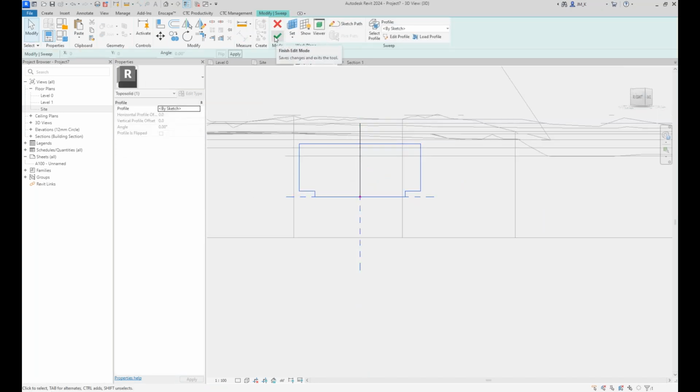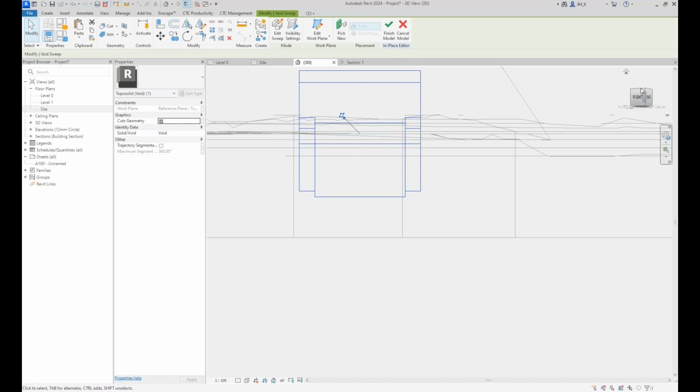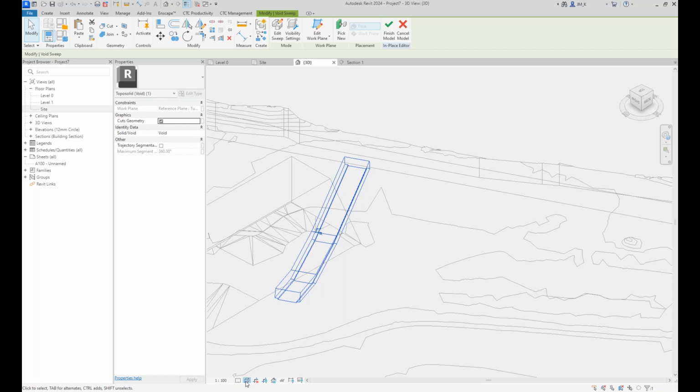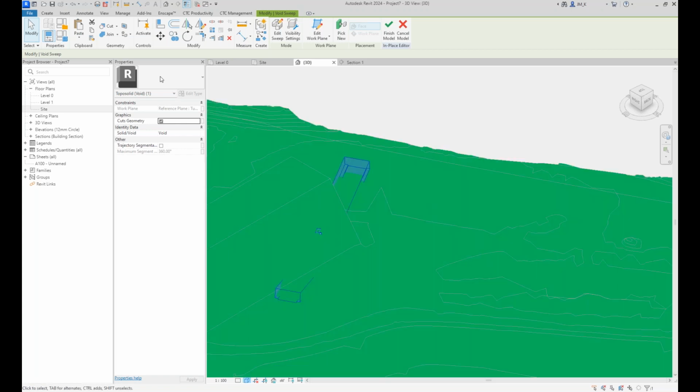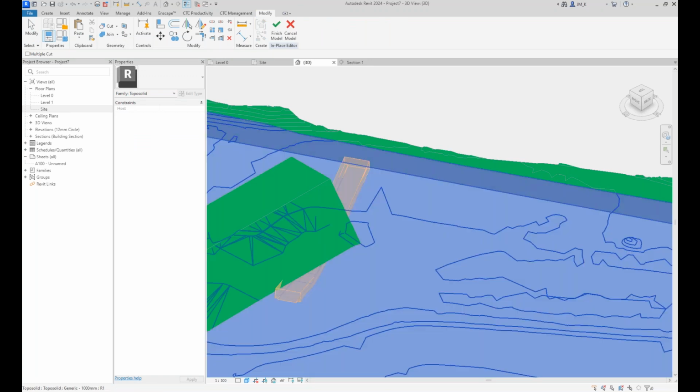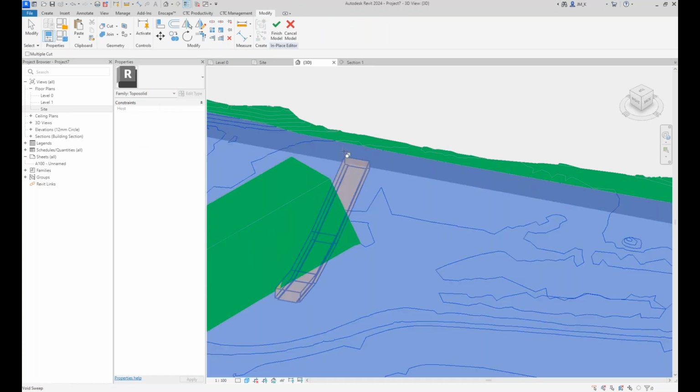Okay. Now I think before we get out of this, before I hit finish model, I have to make sure that I cut. So I'm going to go back to consistent colors, cut geometry. Again, make sure I hit the top of the surface and click the void.